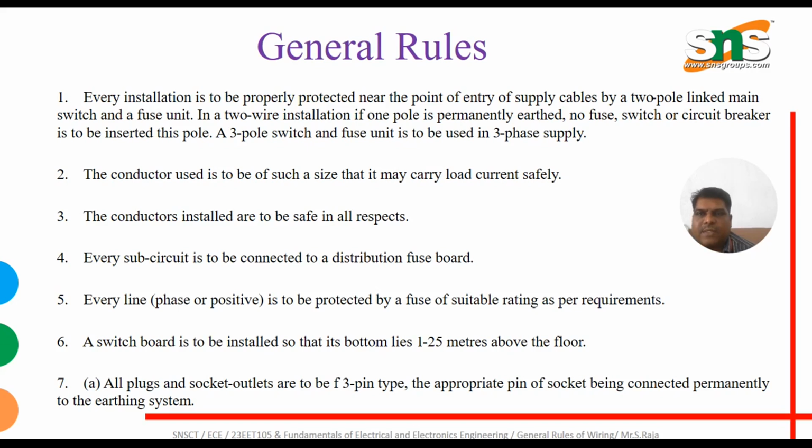The conductor used is to be of such a size that it may carry the load current safely. The conductors installed are to be safe in all respects. Every subcircuit is to be connected to a distribution fuse board. Every line is to be protected by a fuse of suitable rating as per the requirements.